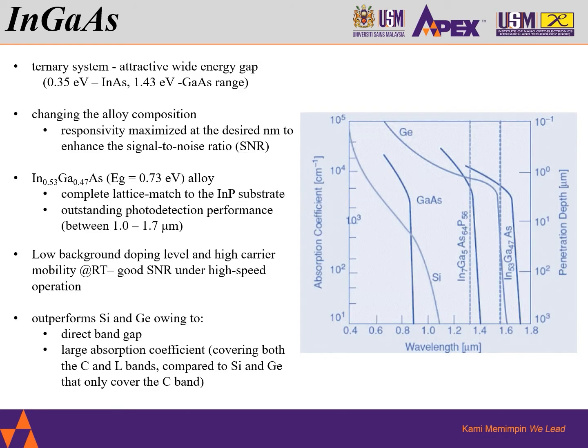The indium gallium arsenide ternary system is attractive for its wide energy gap, ranging from 0.35 eV for pure indium arsenide to 1.43 eV for pure gallium arsenide.